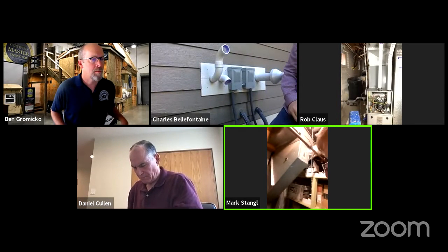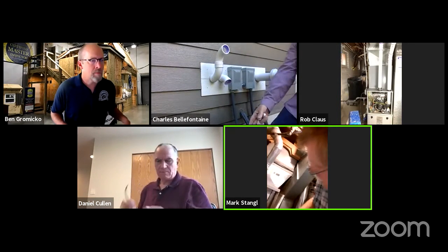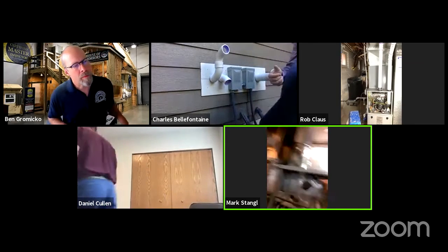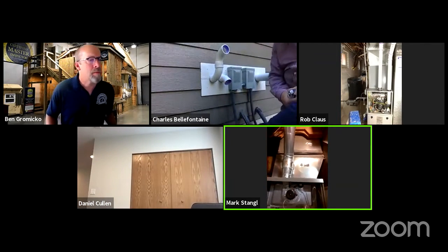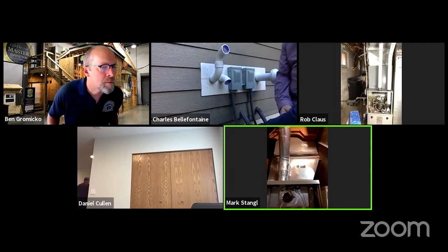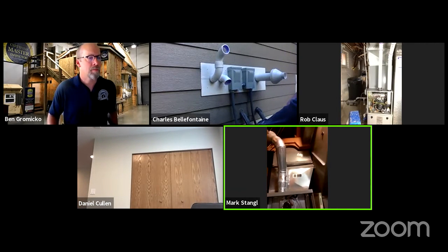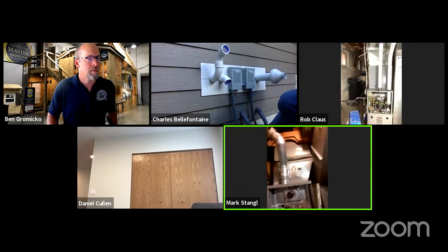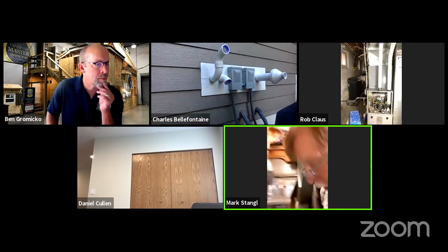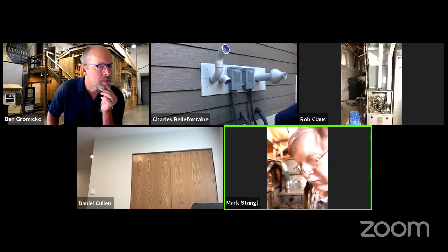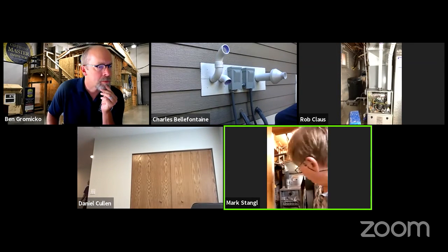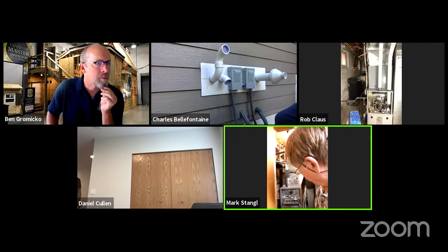Again, this furnace has a diaphragm system here that makes sure that the fan is operating correctly. And then we also have the burner system itself to ignite it, also has its own safety system that will not allow the system to move forward and ignite if it's not operating correctly.